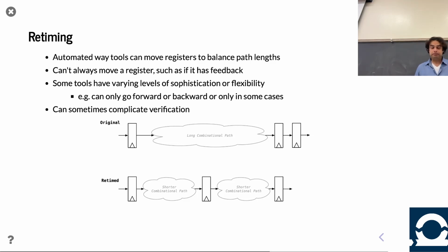But now let's come to verification, right? Maybe verification is based on the values of the registers. Now the registers have different values because you've moved them around in the design. So what do you do? That's something that's been cutting edge for the last 10 plus years. You do register retiming, and now the register semantics have been changed.